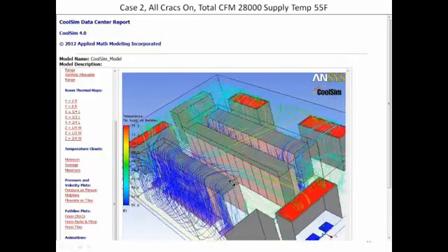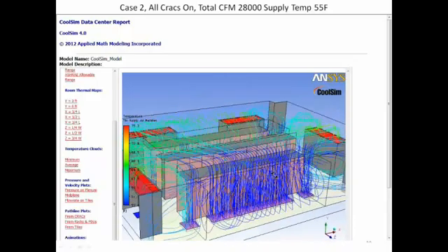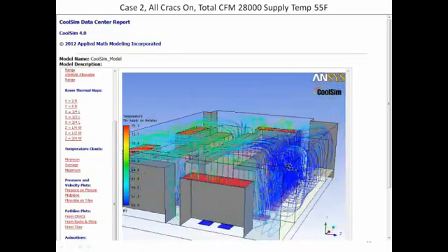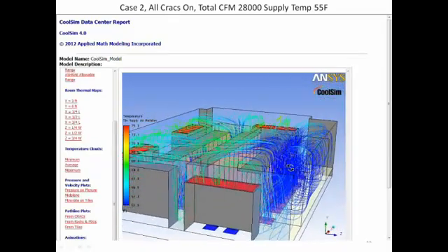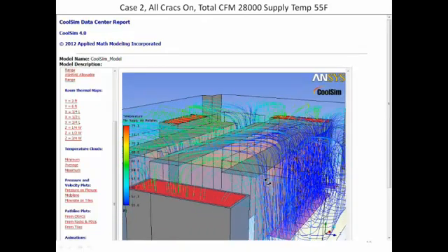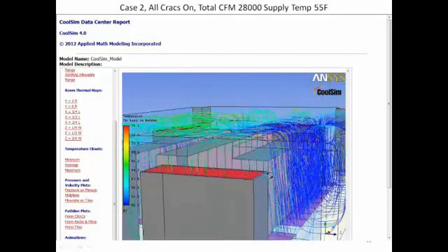A wind tunnel. We talked about it as a wind tunnel. Just way too much airflow, coming right up and going right over those racks and back to those CRAC returns. Yes. So this is a visual representation of the RTI number, which is 54%. And this is the visual for that, right?